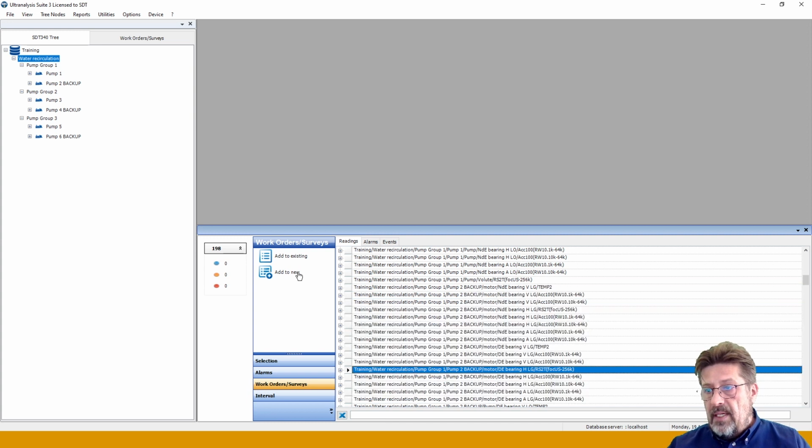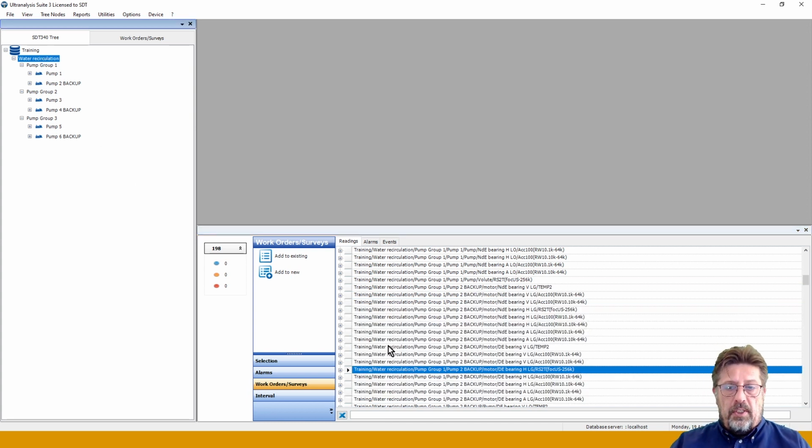And let's hypothetically put another situation here. I have a technician, a process technician, who is sometimes checking valves and all the other stuff. And I can easily ask him, can you please just check the body of the pump, the volute, for cavitation, while you are playing with the valves? Why not? Probably he will say, nah, don't push me into the bearings, that's not my job. But of course, easily I can put the sensor and listen to cavitation and collect data. That's a great job, because I will be playing with valves anyway.